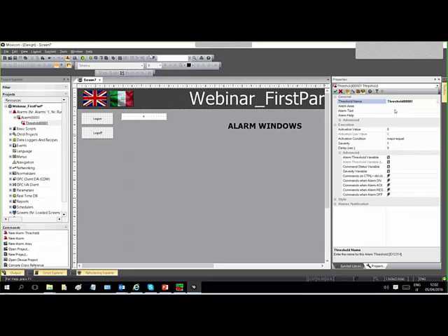You could add here, enter the alarm threshold area as a logical group of alarms. An alarm text, for example, lube oil pressure low. An alarm help: enter the string for the alarm threshold that will be displayed as a help message associated to the alarm text.